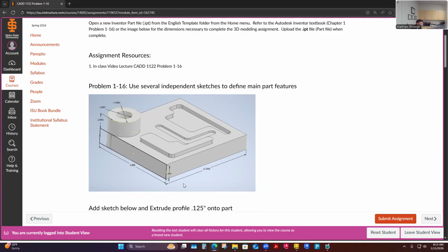I think we learned last semester it's not uncommon in some drafting environments to use probably this view as what looks like the top view as maybe the front view, and set this down as the bottom. Then you'd have the longest width, the most part detail in your front view. That's how we'll detail flanges and stuff. They tend to stand them up on edge. So I could even think that maybe the best front view is actually this top view, which would expose all of the features of this.